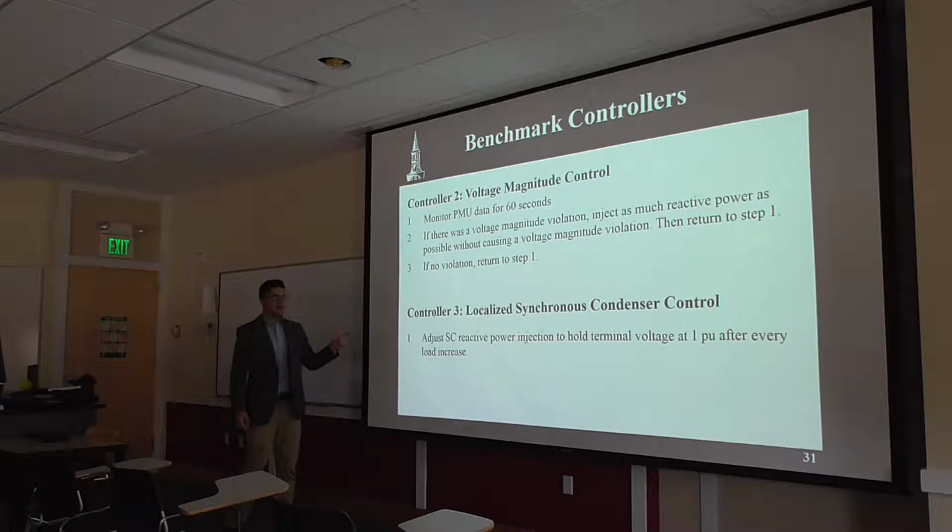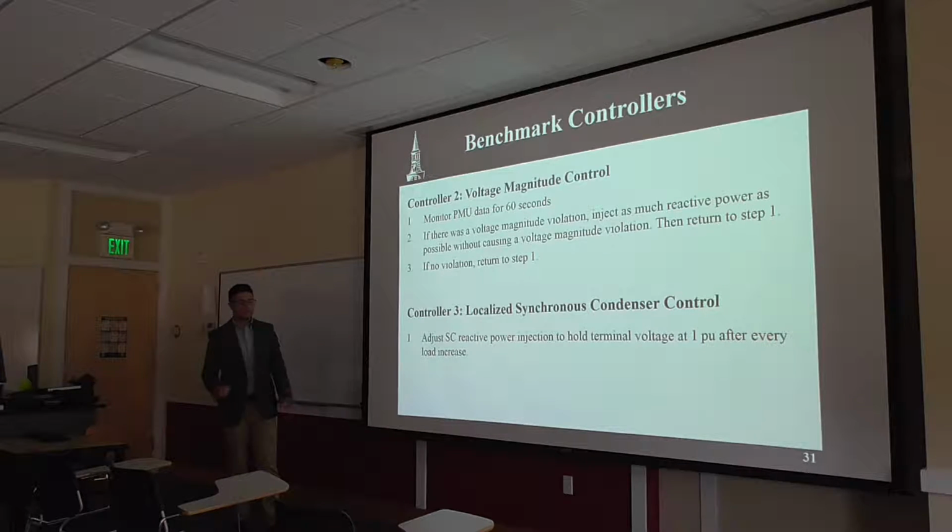Controller three, I'll call localized synchronous condenser control, where this controller is not waiting for any sort of violation on the system. All this controller is doing is using an active feedback loop to continuously hold the synchronous condenser at 1 per unit at all times.